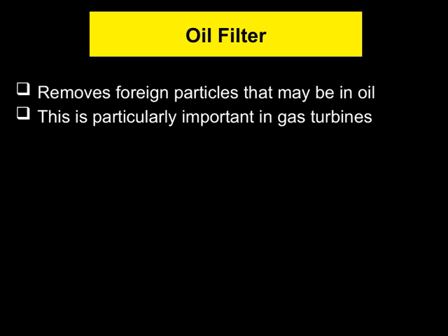Their main job is to remove foreign particles that may be present in the oil. These tiny contaminants can come from various sources, like manufacturing debris or wear particles from engine components. This cleaning process is especially crucial in gas turbines, where even small particles can cause significant damage or reduce efficiency. By filtering out these impurities, we help protect the vital parts of the turbine and ensure smooth operation.